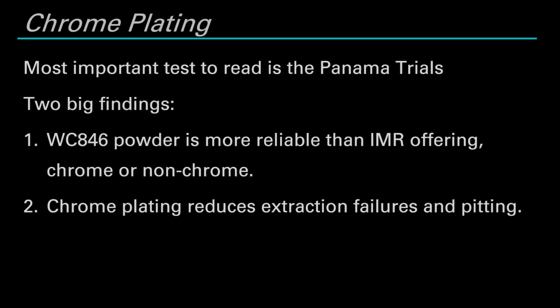And this was all the justification the Army needed to go ahead and greenlight two things. Going forward, all rifles would have the chrome chambers, and all existing rifles would have their non-chrome lined barrels replaced with chrome lined barrels. Eventually, the chrome chambers would become a chrome chamber and a full chrome bore. However, for the reliability of the rifle, the most important thing is that chrome lined chamber.